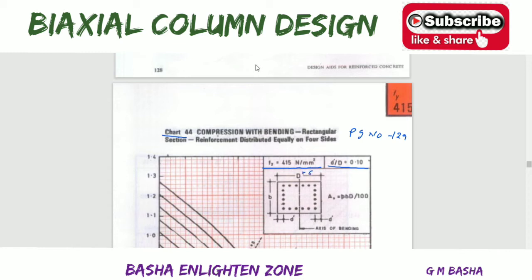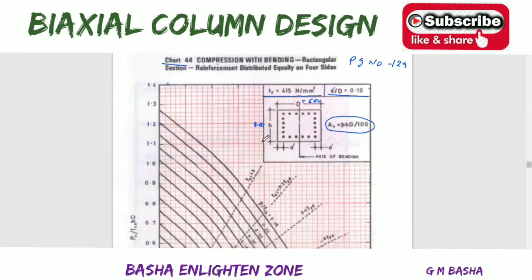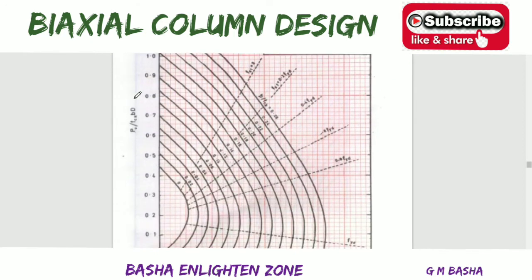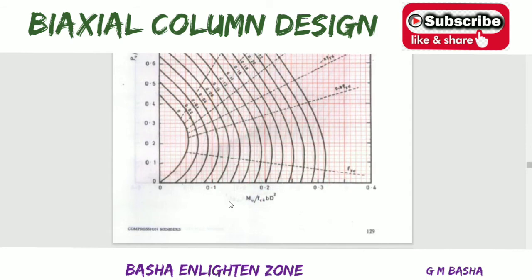So here D will be equal to 600 and this one will be equal to 400. Based on this you can find out the area of the steel in the uniaxial condition. So already we know that, there will be two non-dimensional parameters. One will be equal to Pu by fck b D. Another one will be equal to Mu by fck b D square.